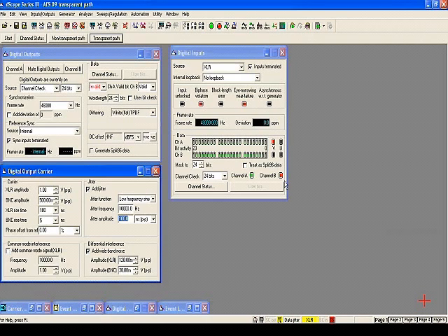Now we're starting to see those errors only on the B channel. You would not come to the conclusion that there's something wrong with the carrier because you've got errors only on one channel. You would think, oh, I've got a piece of equipment that's got a problem on one channel. So this just shows you again the power that you have when you use these types of tools.